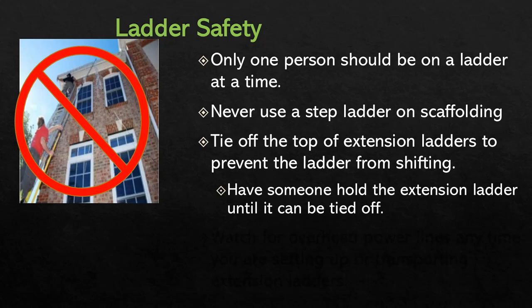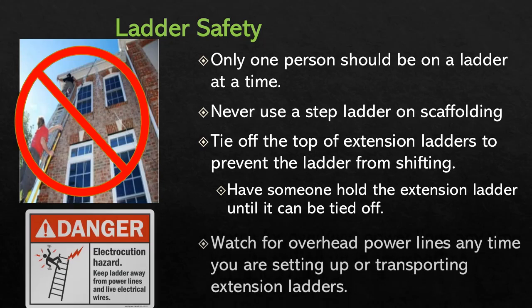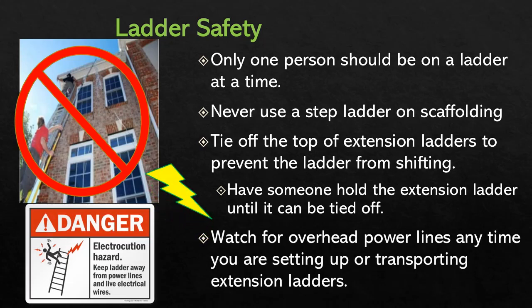As for how to protect yourself while the tying off is occurring, in this case you might have to recruit some help, have somebody hold the extension ladder down at the bottom for stability until it can be tied off. And please, if you're using extension ladders or step ladders or any kind of ladders made of conductive material, always watch out for overhead power lines. And this is not just big power lines, but like the little feeder lines that go into properties. Ladders can reach these surprisingly easily sometimes, so please watch out for this.